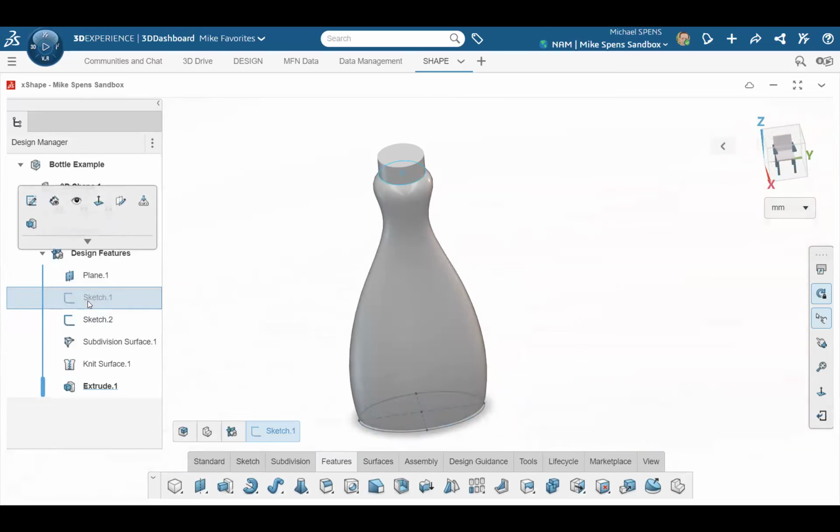Right, that's what I was kind of using to begin to say, okay, I want the top of the bottle to come up to where my neck's going to be. Yep. Because I want my neck to be a specific size, but everything between here and here is just pretty. For the mold for that thing, I'm going to surface mill that mold. I mean, it's a bottle. I'm going to expect to surface mill that thing.